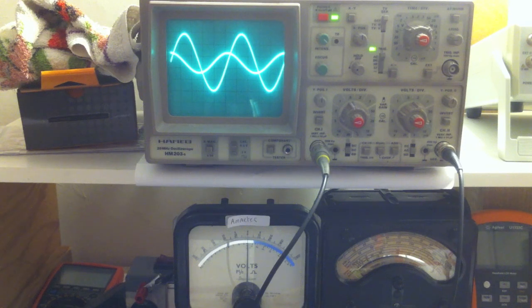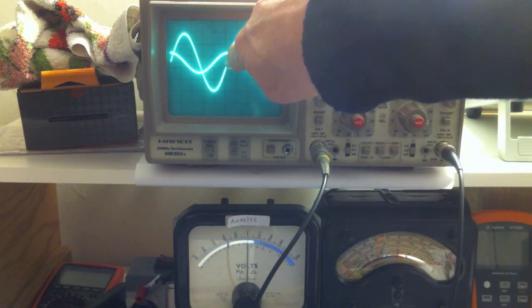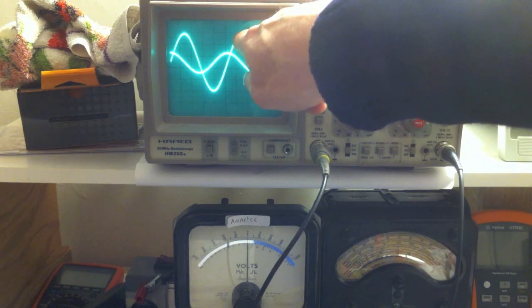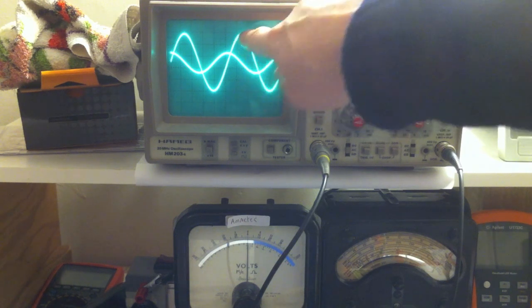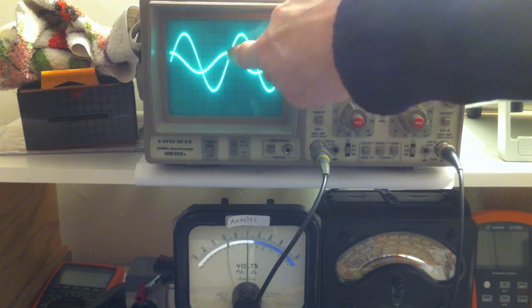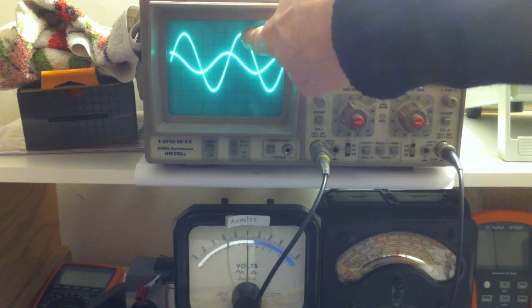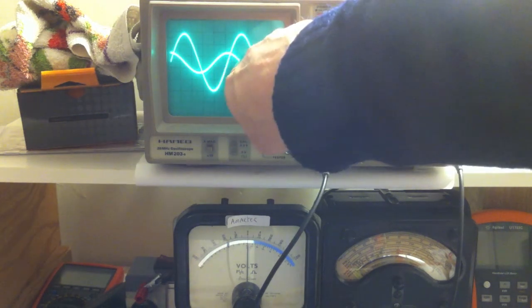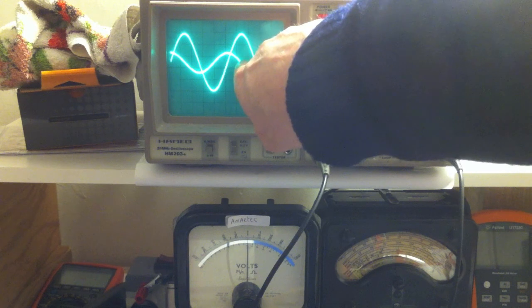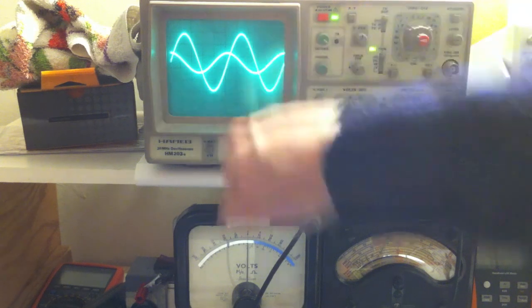And if you understand how the capacitor works, in other words, it's two empty plates initially with no charges across the plates, and then over time the charges accumulate till eventually the capacitor has so many charges on it that the charges add up to a voltage which equals the input voltage. And I'm not showing the capacitor, I'm just showing the input voltage. But at that point, both the capacitor voltage and the input voltage are the same, and that will be the crossover point across the zero, and that will be when there's no voltage across the resistor. So at that point there is no voltage across the resistor.